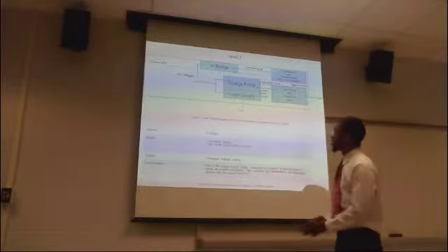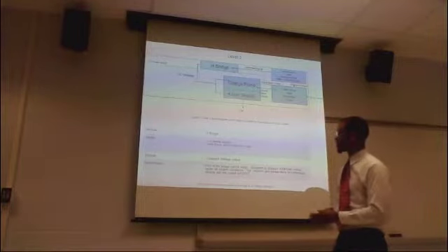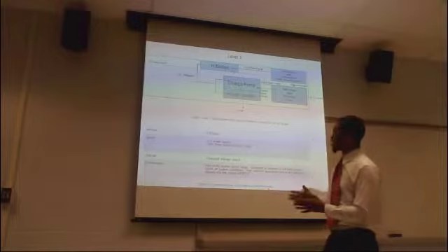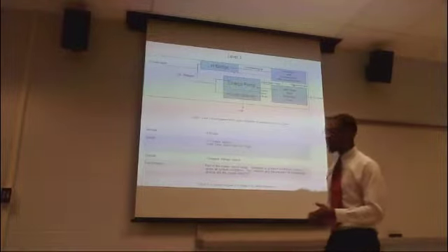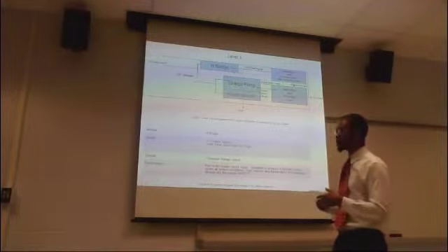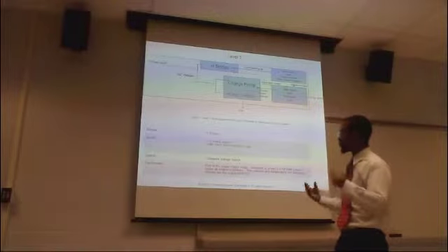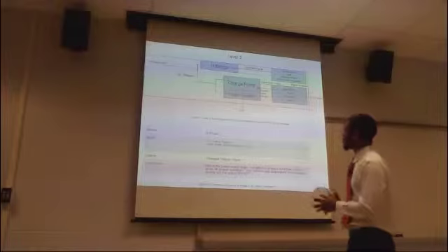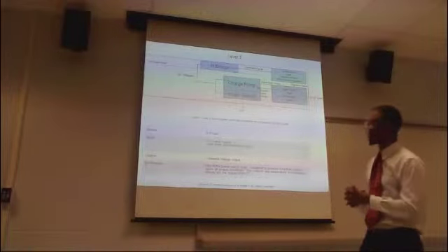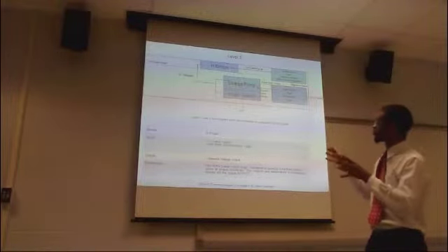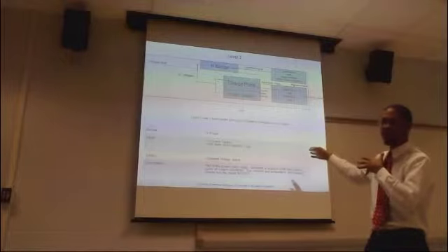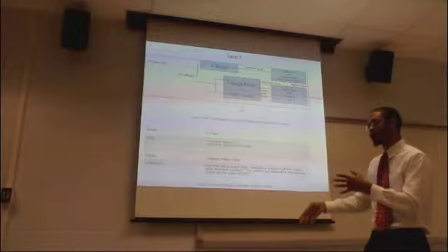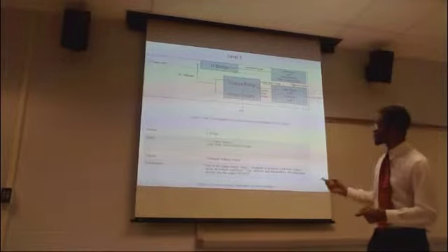Now, for our demonstration, which we will go into later, we'll be looking at the H-bridge. This component is being fed from our 5-volt power supply and our gate-driven protection logic, which is basically our voltage/current regulation and our digital logic inputs. This H-bridge is going to control what is outputted to our DC motors and how we get our wheels turning and moving forward, backward, left and right.